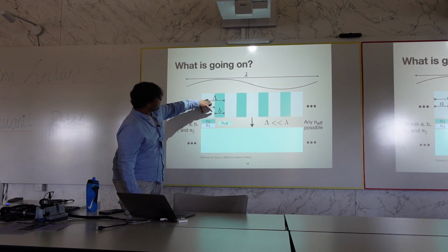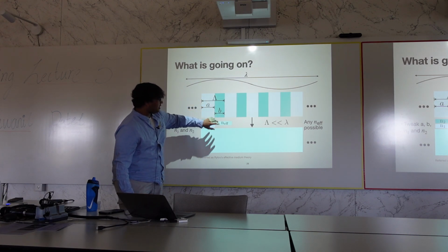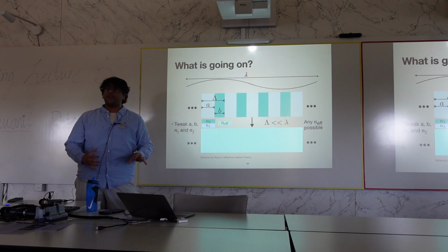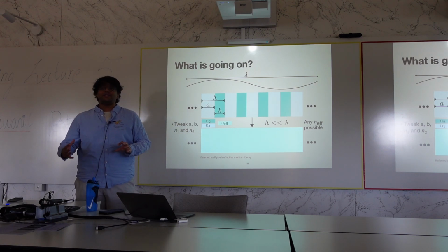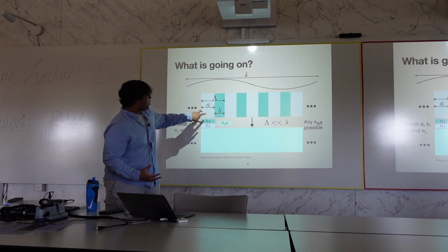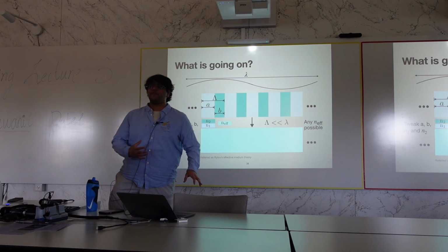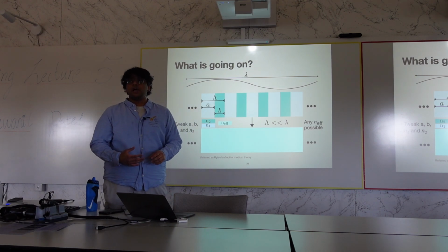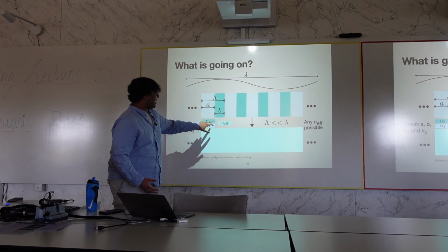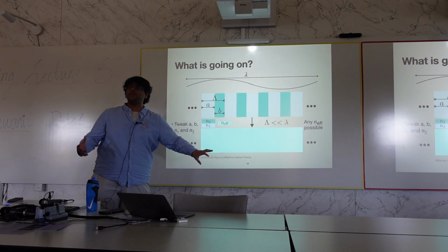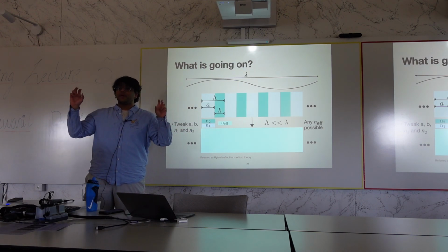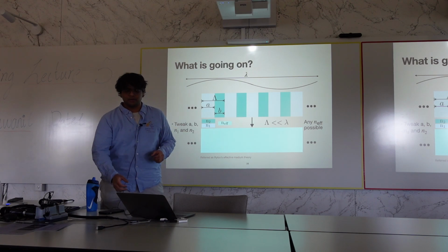If this is material A and material B, then there will be some combination of A and B, and that is basically decided by what width A is, what width B is, and the type of material, like what refractive index you have for the material. So by tweaking A, B, and the type of material, you can make an effective material which you would like to make.